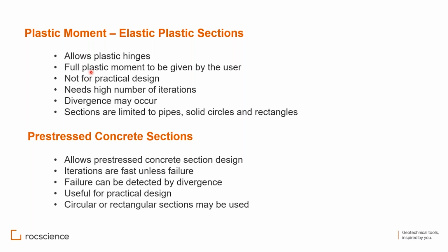In fact, if you go very plastic, it won't be for practical design, because if you have a plastic hinge, the pile will be in a very high displacement mode. So it's not for practical design, but it's for checking whether these sections are okay for you or not. So you can increase the sections until you get a suitable resistance to the moments, shears, and loads applied. Of course, this needs a high number of iterations.